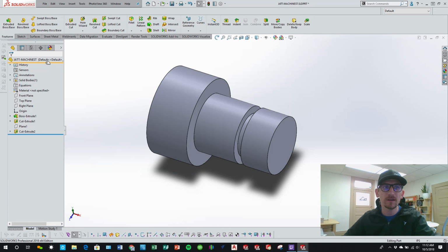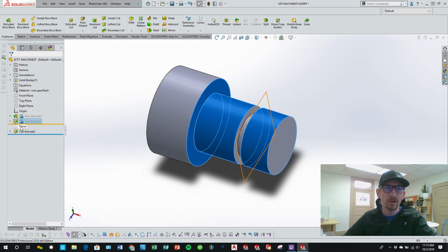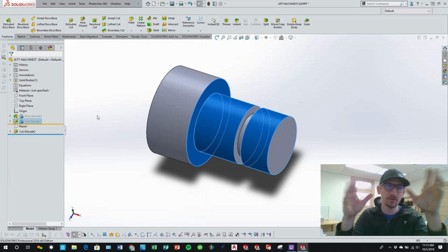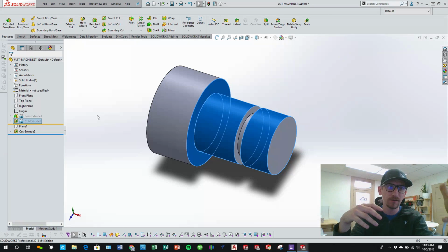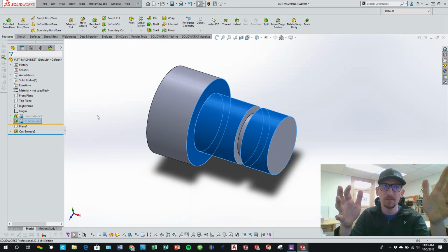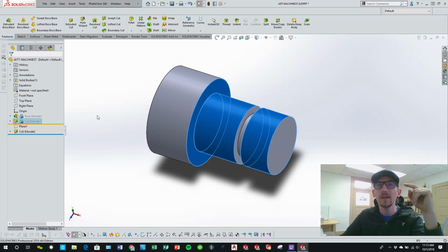It's this orange bar. If I drag this down, SOLIDWORKS will freeze whatever features are above it. And it takes a snapshot of that given set of features and it won't affect them anymore. So if I do a rebuild, SOLIDWORKS is going to ignore everything above it and rebuild everything below that freeze bar up to your rollback bar.